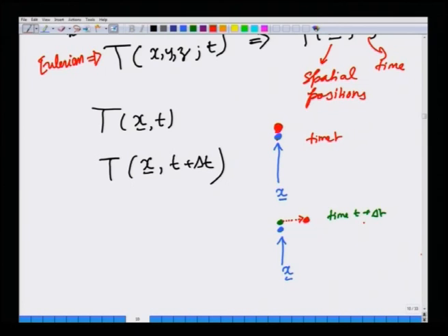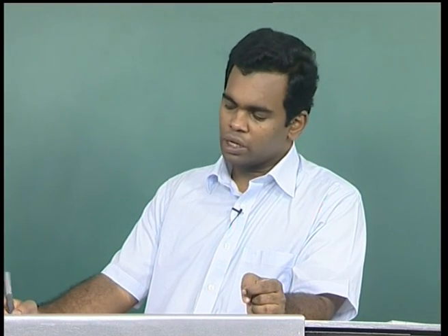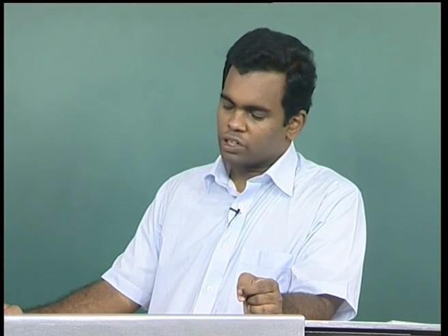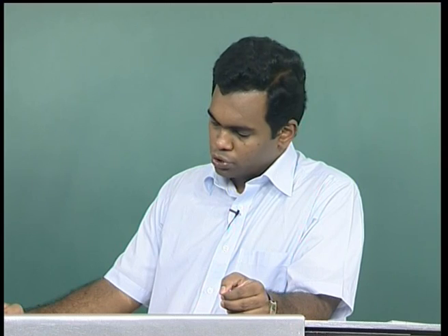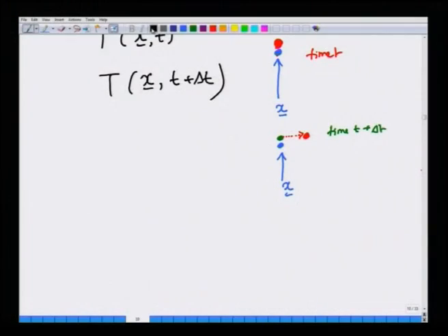So, what we are merely measuring in the Eulerian description is, at a given point in space, the properties such as temperature, velocity, acceleration or pressure as a function of time, without worrying about which material or fluid particle is occupying that location. This is usually okay, except in the case of acceleration.